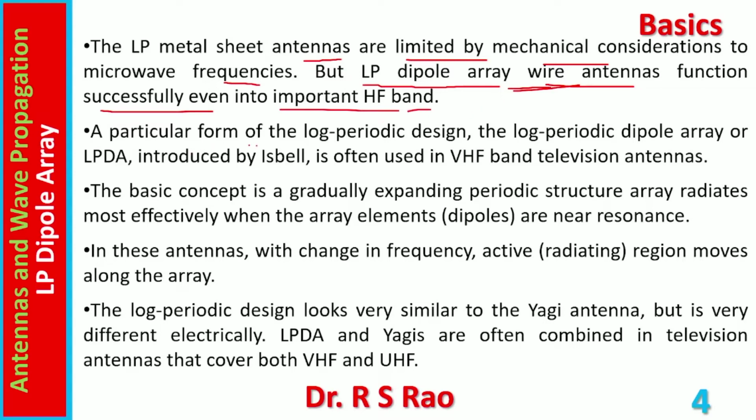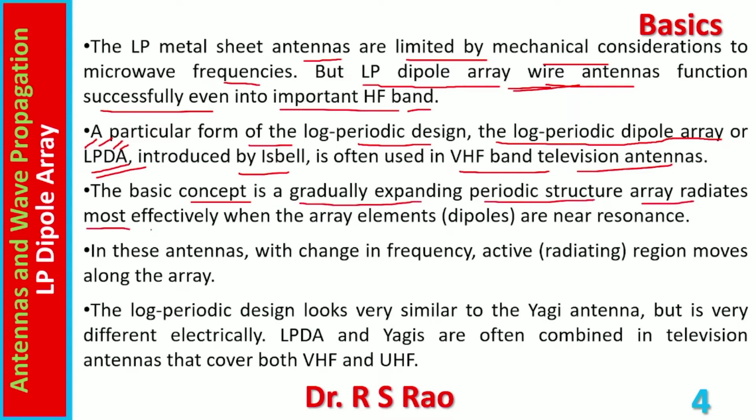A particular form of the log periodic design, the log periodic dipole array or LPDA in short, introduced by Isbell, is often used in VHF band television antennas. The basic concept is that a gradually expanding periodic structure array radiates most effectively when the array elements, here dipoles, are near resonance. In these antennas, with a change in frequency, the active or radiating region moves along the array.